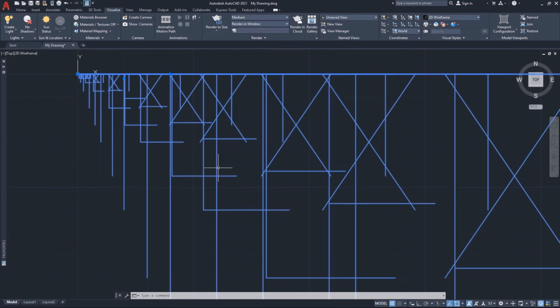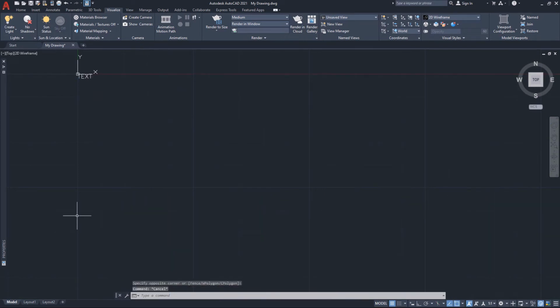One lesson to take away, to be acknowledged at this time, is to not over-assign annotative scales to objects, since doing so simply creates a visually graphic nightmare. Assigning only the annotative scales to be used on any given object is the best rule and method to follow. Hit the Escape key a few times to deselect this text object.